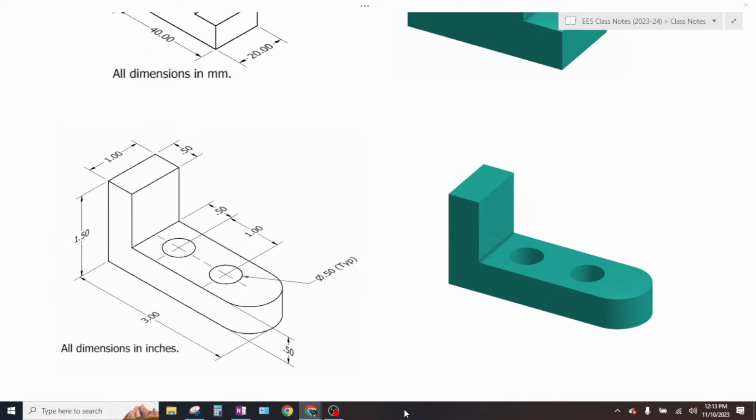Just make sure it's not fully connected. Okay, now, calipers. First thing you should always do once the battery's in and you turn it on is make sure they're closed all the way and click on 0. Don't be a dutz. 0. And it should say 0 point something. Now, we can work in millimeters or inches. What do you want to work in? Millimeters. Okay, we will work in millimeters. So make sure that you push the mode button on the left until it says millimeters. It's going to go to the nearest hundredth of a millimeter.